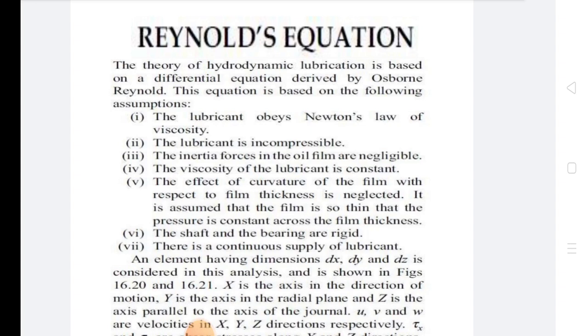The assumptions. The theory of hydrodynamic lubrication is based on the differential equation derived by Reynolds. This equation is based on the following assumptions. The lubricant obeys Newton's law of viscosity. The lubricant is incompressible. The inertia forces in the oil film are negligible. The viscosity of the lubricant is constant.